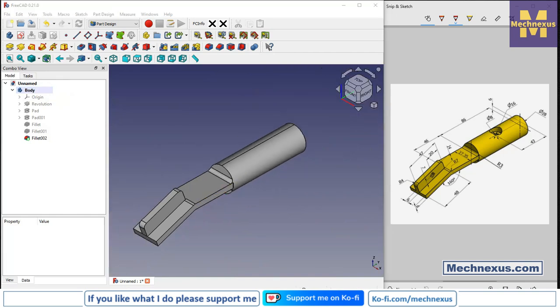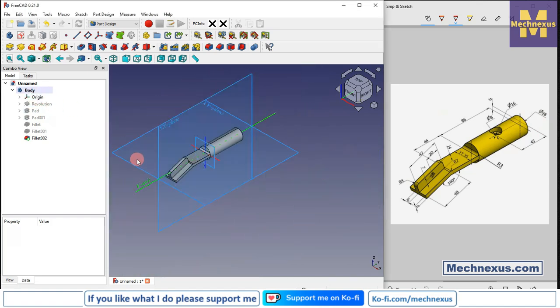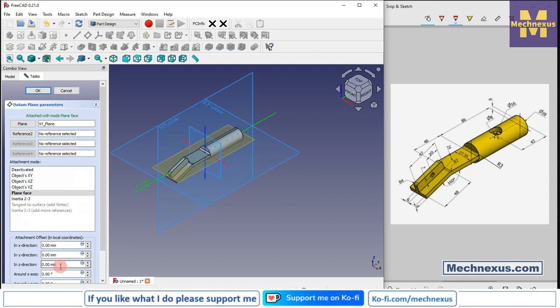Now we will create this hole. So it is a diameter of 28. So we will on our plane and select this plane, and if we wanted to insert the tangent plane, then we will create a plane at a distance of 14 mm. So select the top plane and click on the datum plane, and in a Z direction provide the 14 mm.